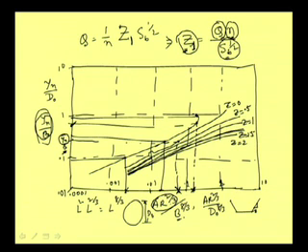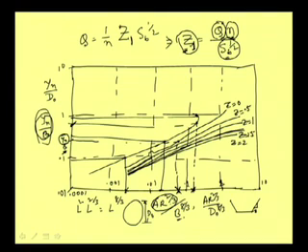Both these values will give you a different normal depth. Of course, the difference in these depths is very small, but in reality also in a circular channel, that is why we say that for higher discharge we can have 2 normal depths. Probably you remember when we started uniform flow, we were discussing normal depth, and that there is an exceptional case in the circular channel.